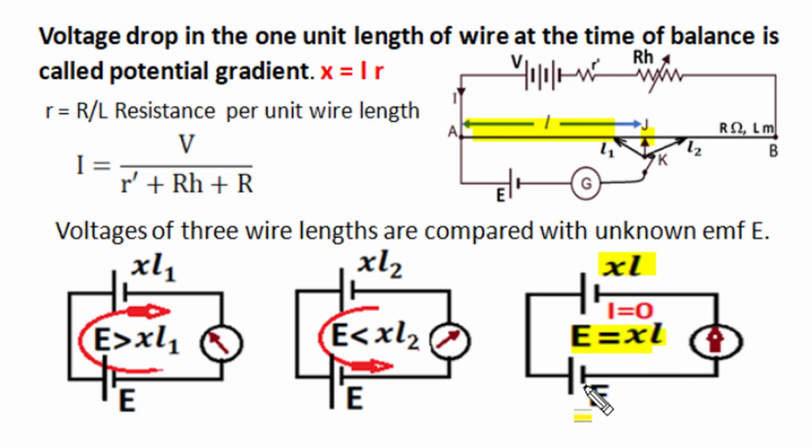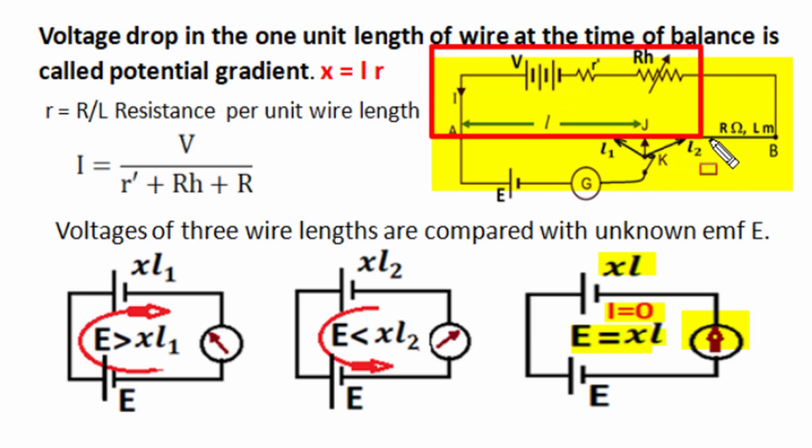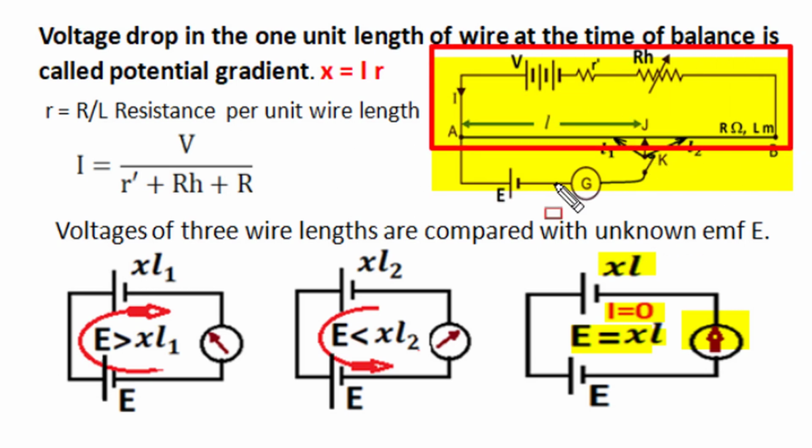balance of the two voltages, there is no net loop voltage and there won't be any current flow in this loop. So the galvanometer indicates null deflection at the center zero position with zero current conditions, and this particular condition is known as the balance condition of potentiometer measurement, and the potentiometer circuit is used only at the time of balance. And in this balance condition, the primary circuit of the potentiometer won't draw any current from the secondary measured circuit.